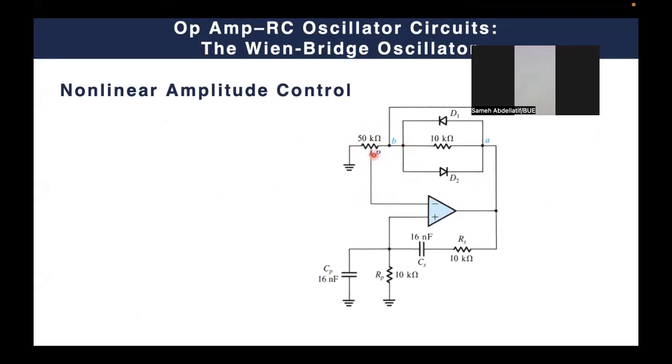This simply means that you have here a split resistance with a factor called B. So between the ground and this point, we have, for example, 50K multiplied by B, and between this node and this node, we have another 50K multiplied by 1 minus B, so that B is the tuning parameter varying from 0 to 1 to control the value of these two variable resistors.